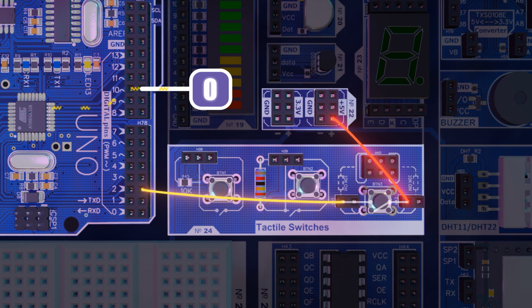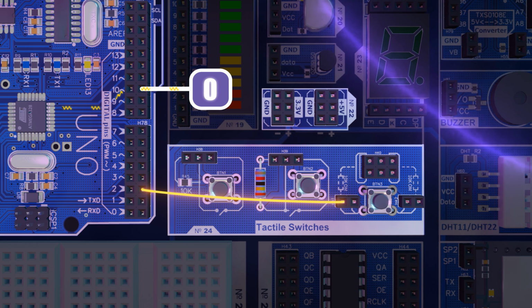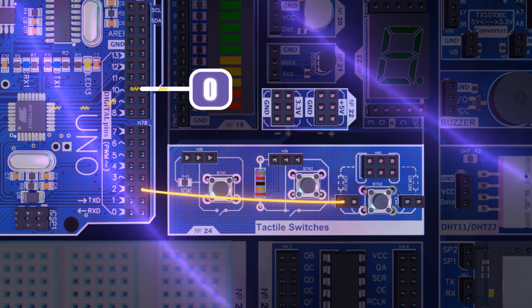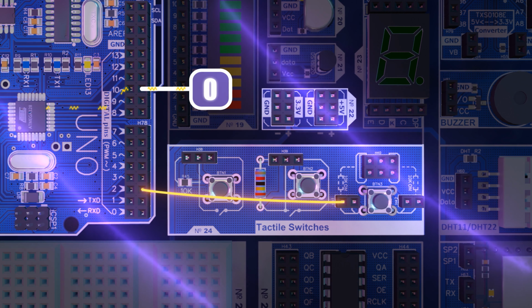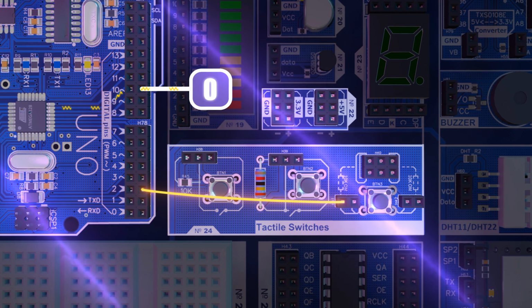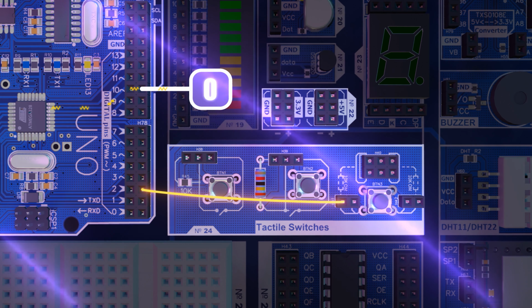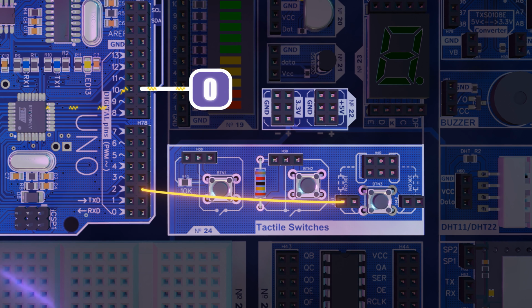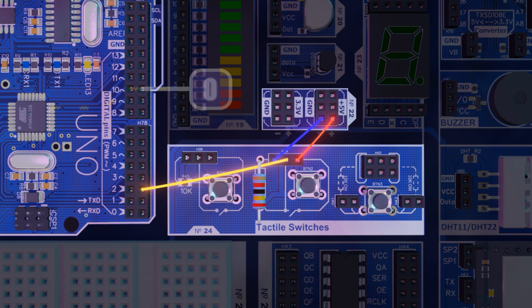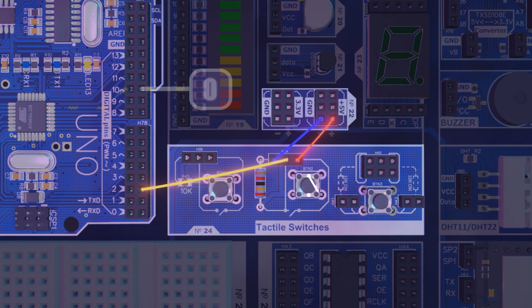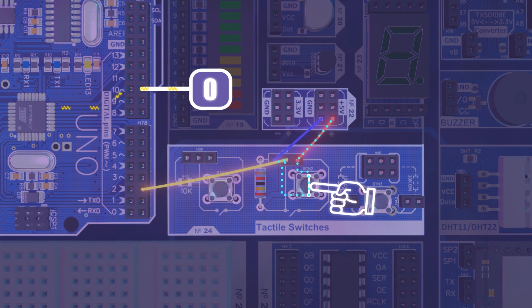In addition to that, if the output of the microcontroller is not connected to either plus or minus, then any signals passing nearby will interfere with this contact. Because of these noisy signals invisible to us, the microcontroller will falsely work as a pressed button. To prevent this from happening, we use a pull-down resistor. When the button is pressed, the current will follow the path of least resistance, that is, pin number 2. But as soon as the button is unpressed, the charged capacitor will discharge to the ground through the resistor.